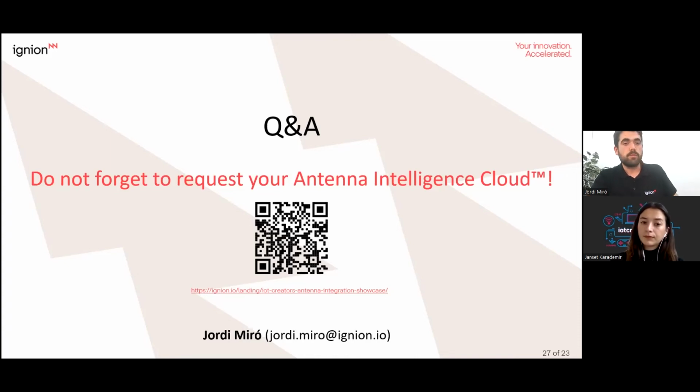So as I mentioned before, the antenna portfolio goes from very small antennas to large antennas. So I think, yes, there is no problem to replace an existing antenna in a design when a PCB is already produced. Bearing in mind the design recommendations, for example, in the case of antenna clearance. So if any change can be made, maybe it will work better.